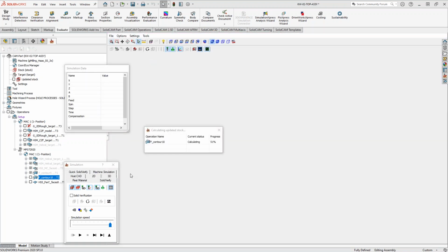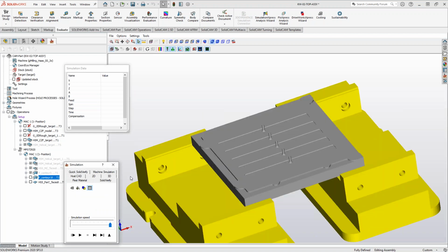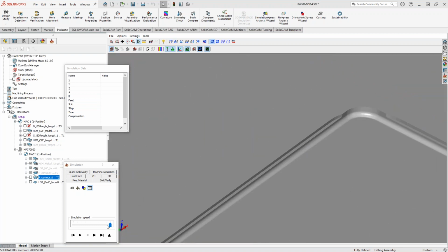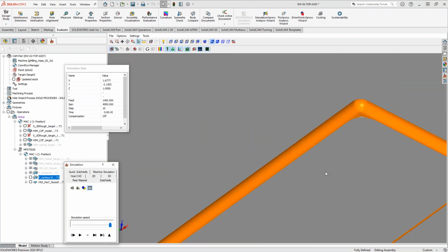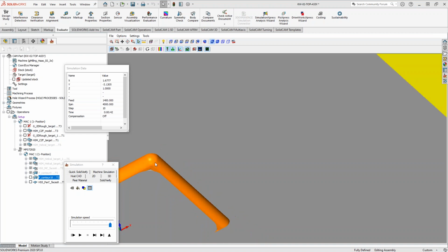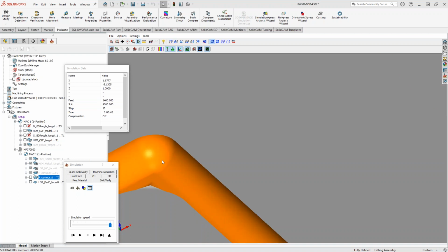Just bring the stock up to date. And again, the bullnose is a standard shape, but it still could be used like a shape tool. So if we take a look at my corner there, if I run this through, I get my corner. I get my nice corner formed by my tool. In this case, you saw me make a tool that is on size, but whatever you've got there. This corner is formed by that tool. It looks like a nice, smoother looking corner. Hopefully that makes sense.